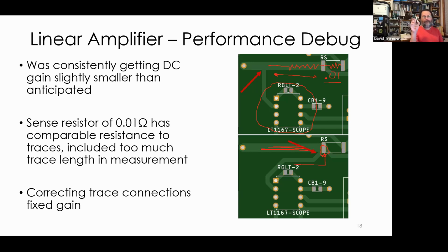This falls under the heading of 4-wire measurement. If you want to measure small resistances, you have 2 wires for current and 2 wires for voltage.